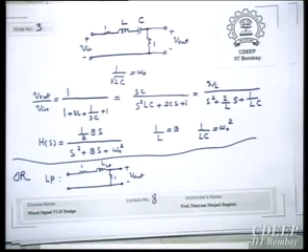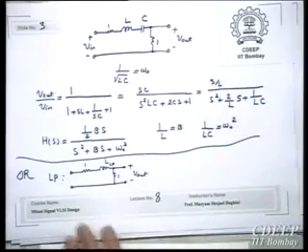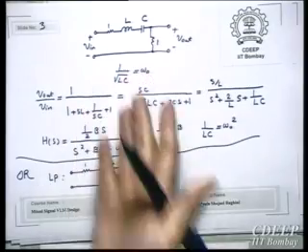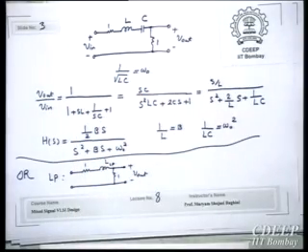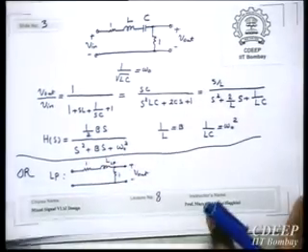That give you all of them by using 3 to 4 op-amps. Therefore, they are essentially multifunctional biquad modules. Then they are used as a standard way of designing multi-order filters. So then, after this, when you are able to get this, then the problem is solved, because then converting it to any sort of filter, including GMC, including active RC, is very straightforward.